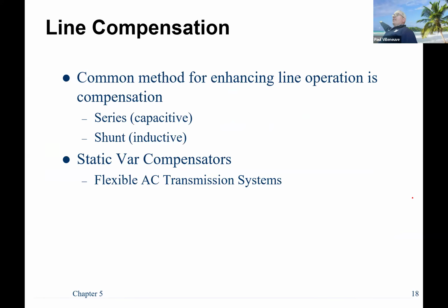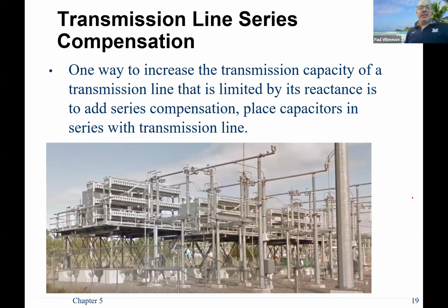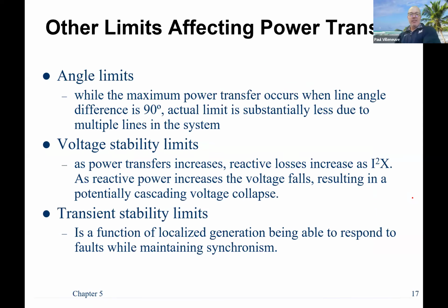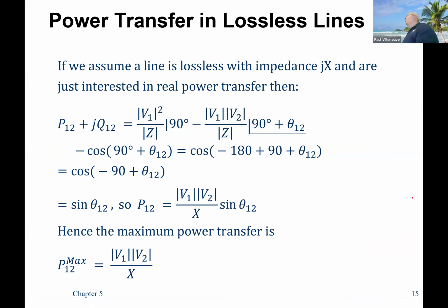So in Orrington, there are series capacitors. That picture right there is of the Orrington substation. That's just a Google Maps picture. And those three, I don't want to call them boxes, but structures, those are 3 series capacitors. The whole purpose of it is not to improve the reactive power of the line. It's actually to improve the power flow through the line. So those work really well. And both lines coming out of Orrington have static series compensators for it.